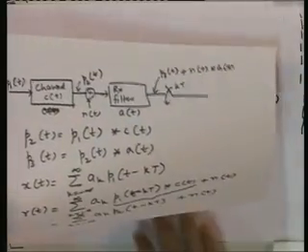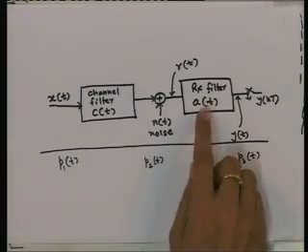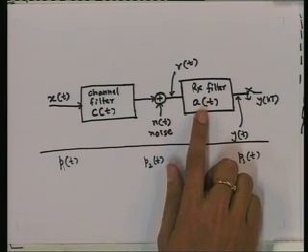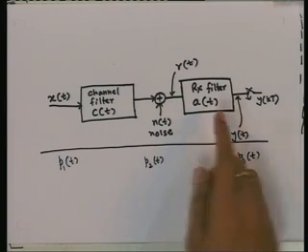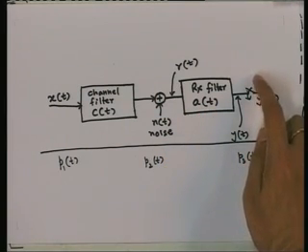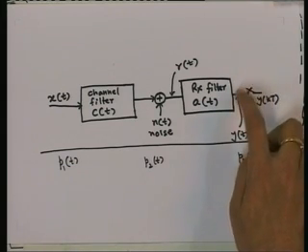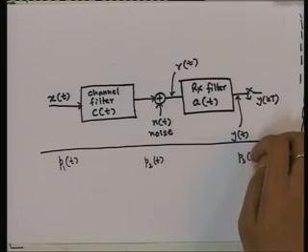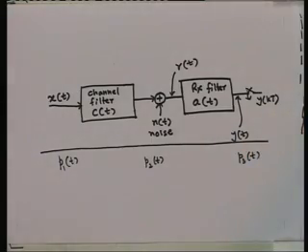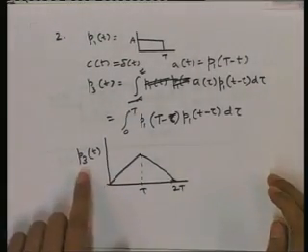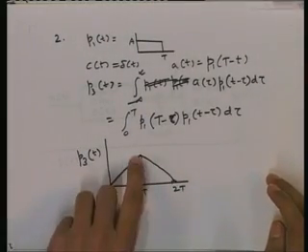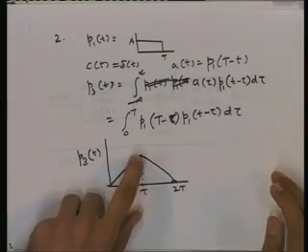Then we have seen that if we take such a matched filter, we should sample every capital T seconds, because that gives us the maximum SNR. There p3(t) has the maximum amplitude, as we saw for two different examples. For the rectangular pulse, p3(t) has maximum amplitude here, which gives the maximum scaling of the symbol.